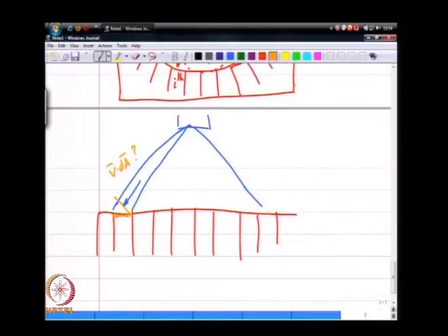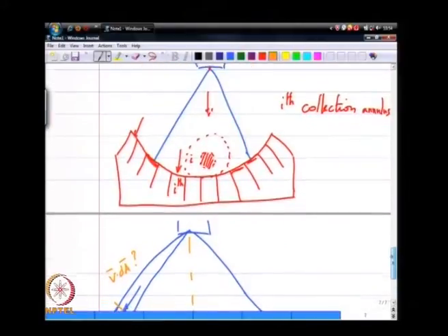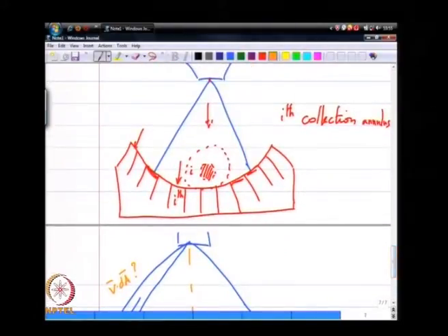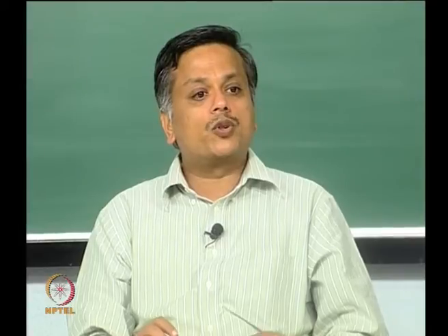So, in an inline design, the angle between the velocity vector and the dA area vector is different, and that causes, even though I am thinking that I am exposing the liquid to the same cross sectional area, the cross sectional area that the flow actually sees is different depending on how far out away from the center line that particular sector is located. Whereas, if I have them all arranged in the form of a circle, then the angle between the area vector and the velocity vector is essentially close to being 0.